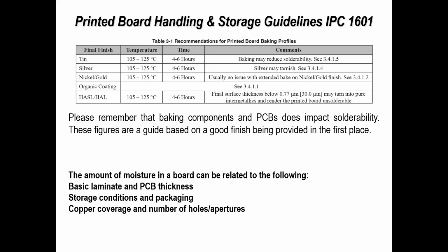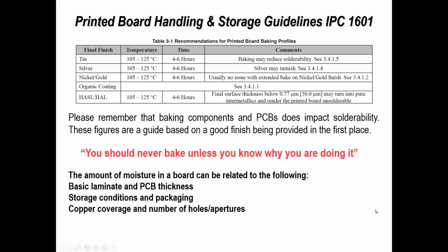So it is incorrect for specifications to say bake for a certain number of hours, because every board is different. However, it's easier, and that's why people do it. But remember what I said a few slides back, never bake a board unless you know why you're doing it. And the reason being that sometimes people have a problem once, possibly with a supplier or a particular board, and they bake and it overcomes the problem, but they do it forever. Rather than finding out, has the board got better? Have you improved the quality of the board or improved the design or some other aspect? And you don't need to bake anymore.